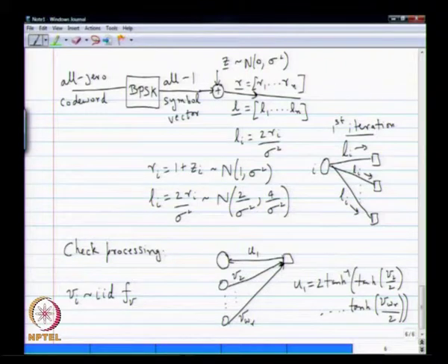Technically, in terms of probability it is a solved problem. You must have learned this at some point in your probability course. It is a solved problem to find the PDF of U given the PDF of V2 to VW. So it is only a question of implementation detail to figure out how efficiently I can implement that transformation. Using the function f of x equals log tanh of mod x by 2, you can implement it very efficiently. Let me quickly show that.